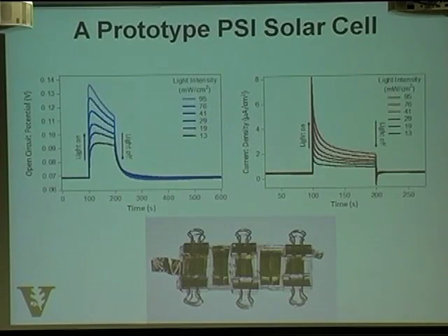We've also made, through this process, a kind of a handheld photoelectrochemical cell, and very crude. I'll show it there at the bottom. It's just essentially a glass substrate on bottom, some gold-coated silicon wafers in the middle, an indium tin oxide glass coating on top. We put these together in series. Look, they're in parallel. They're in series, running through, and we clip them all together with some simple clips and shine light on it, and we are able to get some curves there.